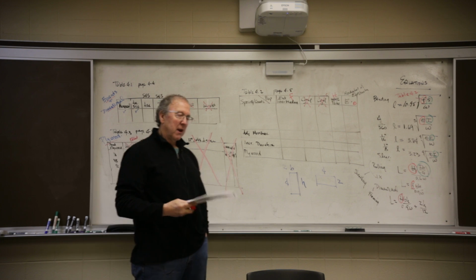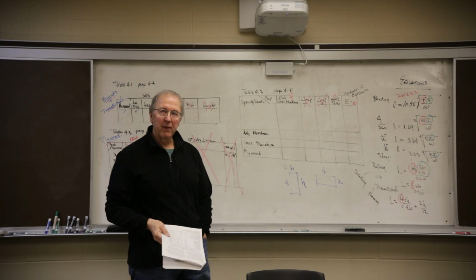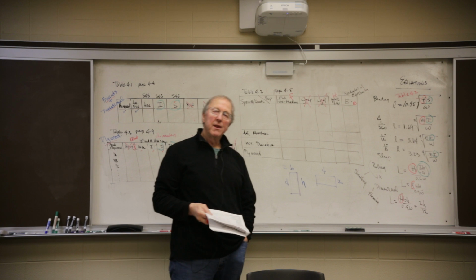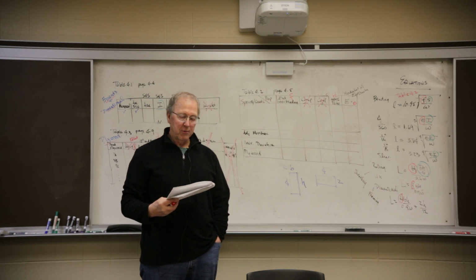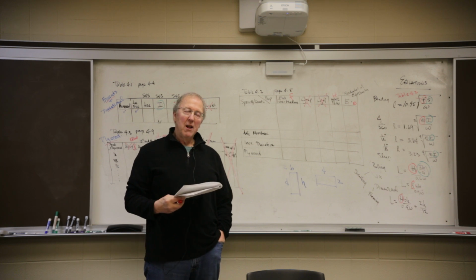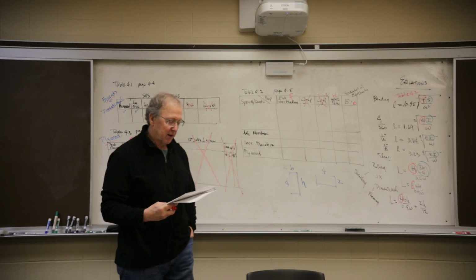What does that mean? 19% is standard in the industry. If you go to Lowe's and Home Depot, the maximum moisture content they can sell you is 19%. So that's what we buy. Lumber with 19% moisture content.